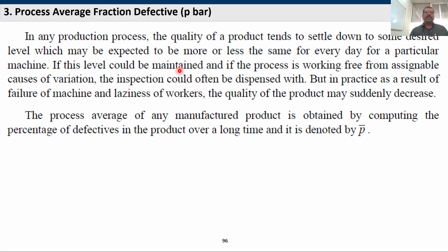Okay, for example, if the machine has settled, you will be checking continuously, every day, then after every 2 days, after 3 days, or every week, and it is constantly giving the same amount of defective items. The acceptance rate is also the same, like 95 percent or 90 percent constantly. In that sense, we can know that instead of taking a sample every day, maybe we can take samples from the machine weekly, like that.